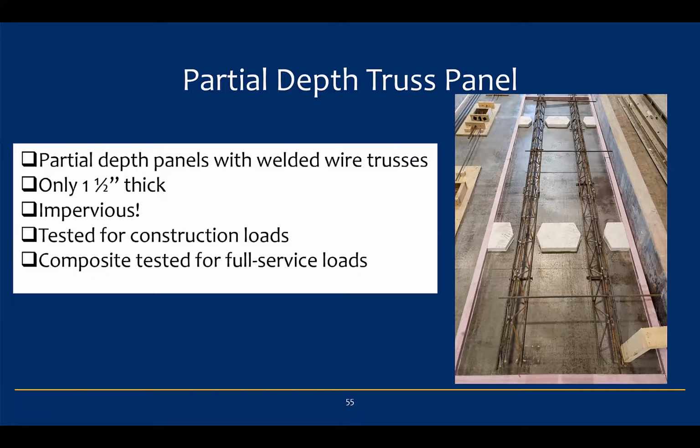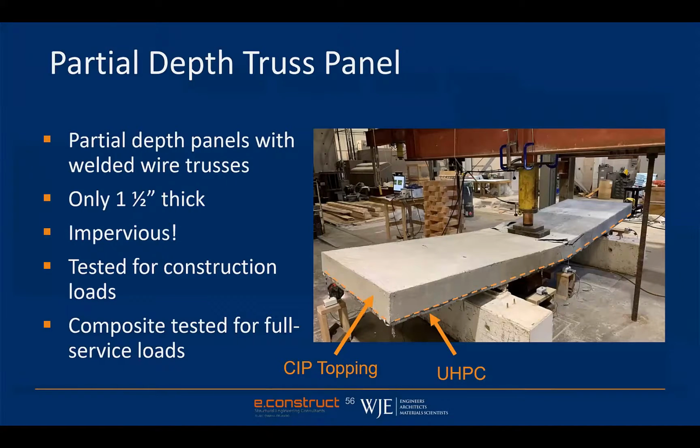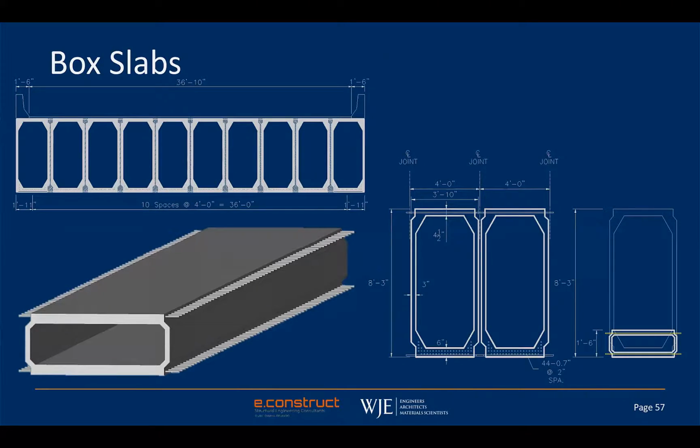So if you're in Florida and you have low bridges and salt water is shooting into the bottom of the bridge and eating it up, you'd have that layer of ultra high performance concrete that protects the underside of the bridge. It ends up being topped with cast in place concrete topping. We tested a couple of specimens, and they seem to work very well. So that's an area that's worth pursuing with a more detailed research program.